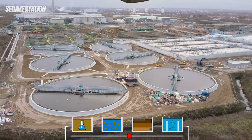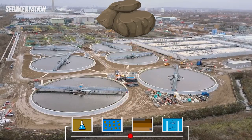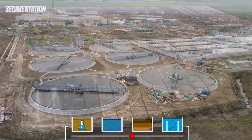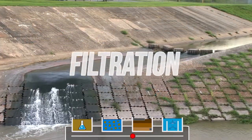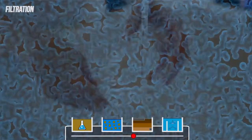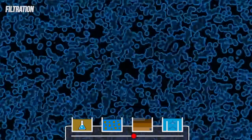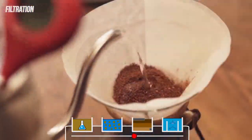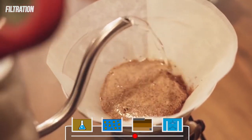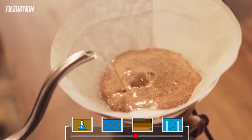After the majority of solids are removed from the water during coagulation and flocculation, followed by sedimentation, the water flows over weirs to the next step: filtration. The water at this point will start looking clear, but there will still be bacteria and very small suspended solids in the mix. The filtration process will seek to remove the remainder of the suspended solids and bacteria to further bring the water up to snuff.